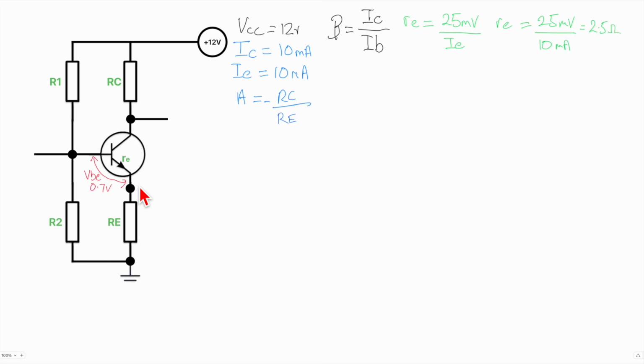What about the voltage we want here? This is where we're going to use a rule of thumb. The truth is, you probably don't need very much voltage on the emitter at all for it to work. I've seen people argue that as little as 500 millivolts would be sufficient. The rule of thumb is you would want to put a volt at this point on the emitter.